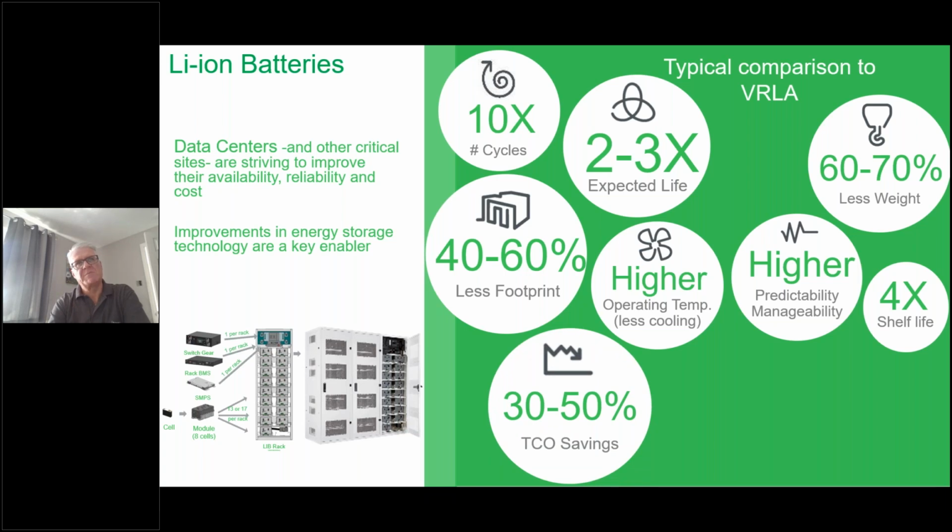The result of this expected design life, if we look at the TCO, the total cost of ownership, is that we could expect perhaps 30 to 50% savings. That is primarily because with a lithium-ion battery, you may get 12 years, or even 15 years life expectancy. You might have changed your VRLA battery 2 or 3 times before you need to consider what's going to happen down the road for the lithium-ion.